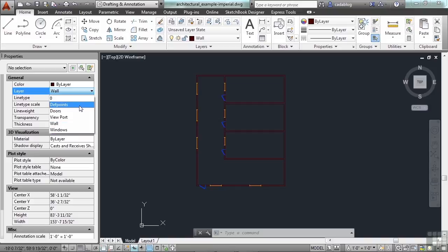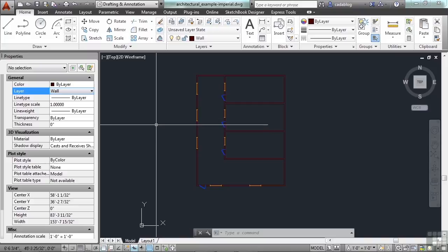This is a very short list, to be quite honest. Most drawings, well, there is no most drawings. Many drawings will have so many different layers in it, it could astound you. Where I'm currently employed at full time, our template file has over 2,500 layers in it. It's absurd the amount of layers. So that's why you have to understand how to use layers, when to use them and when not to.